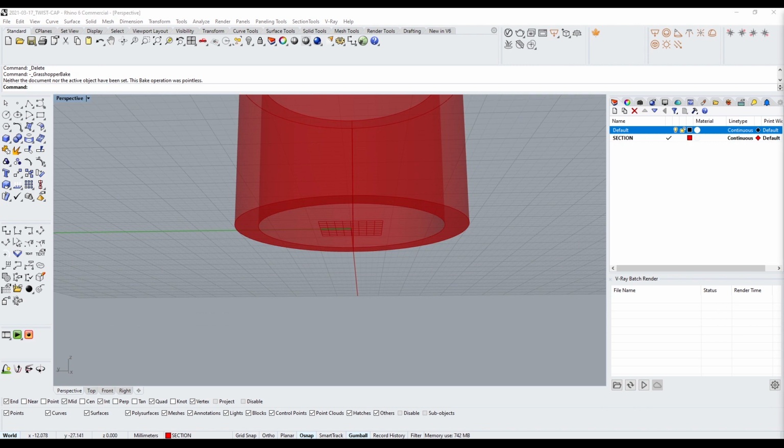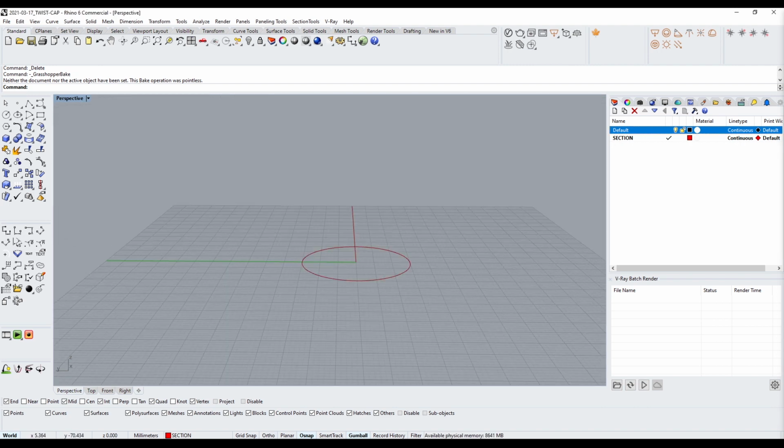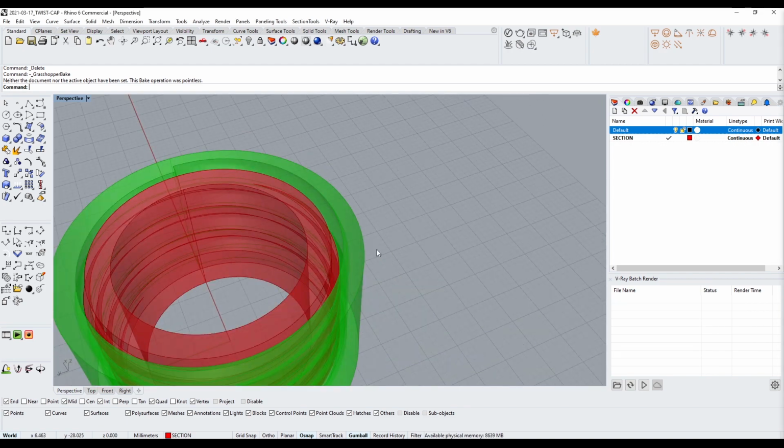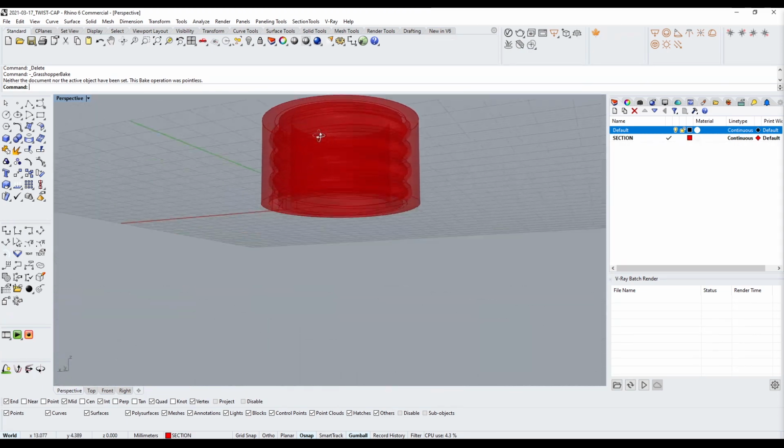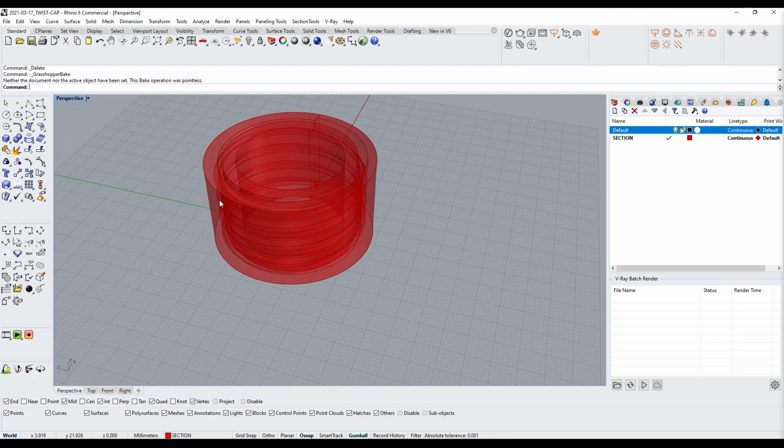And now we can disable the preview on all of this stuff, including this. And we can bring back the twist. Why? Because now it did a Boolean union between the one that's hollow. So this is perfect. You can create a bunch of different size caps and just use them for 3D printing. Whenever you're creating an object or something, this will create a connection between two objects too.